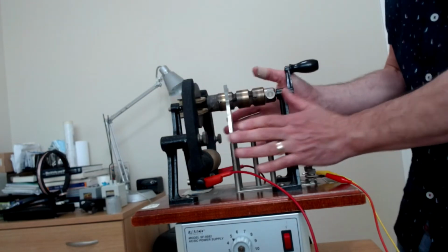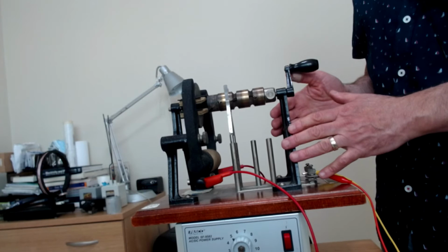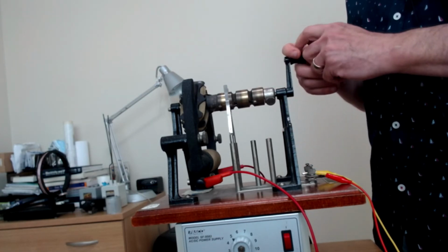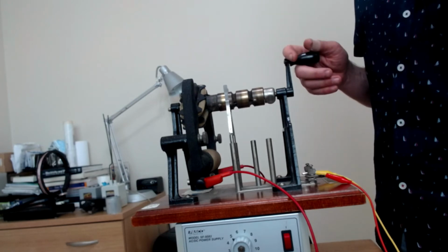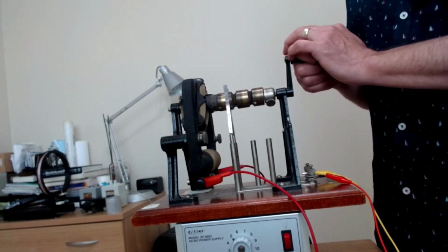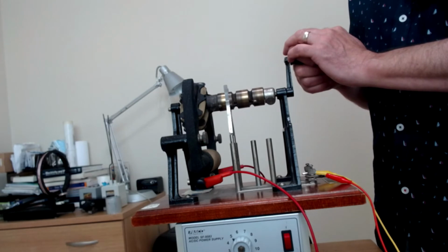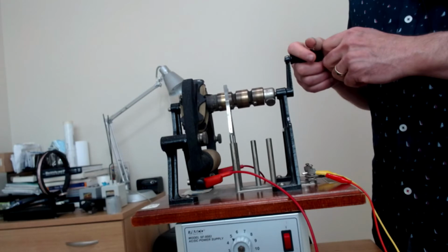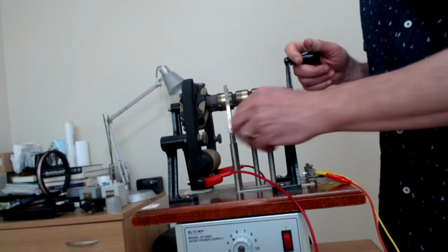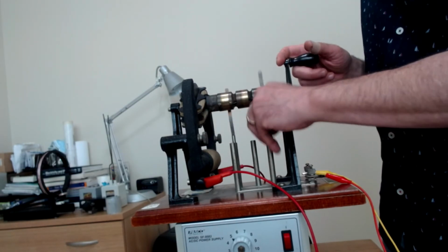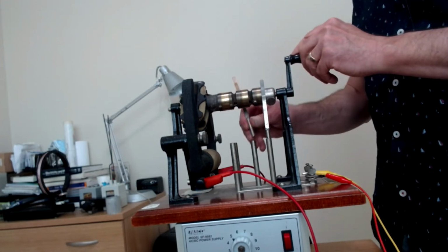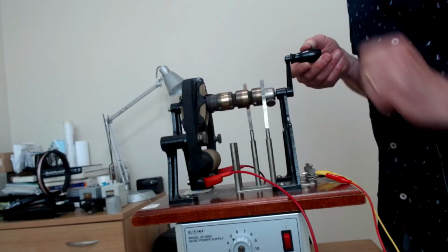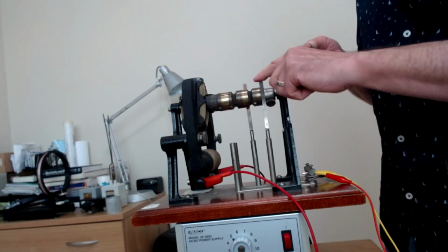Remember, this is the motor I showed you a couple of weeks ago where I had the split ring commutator. This is generating the absolute value of that equation I showed you a little earlier. And it's really because of the split ring commutator. If I wanted to produce AC, then I'd have to have 2 separate electrodes for commutators. I would connect the brushes to these two like you see right here. Can you all see that?